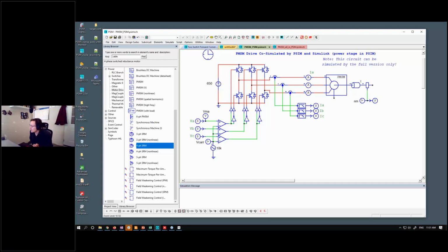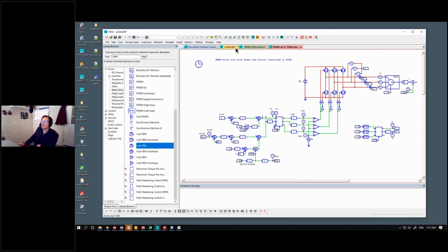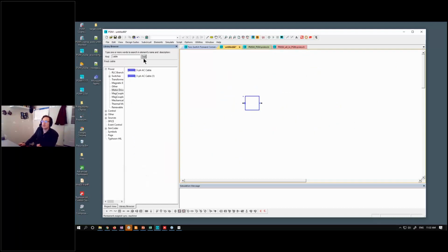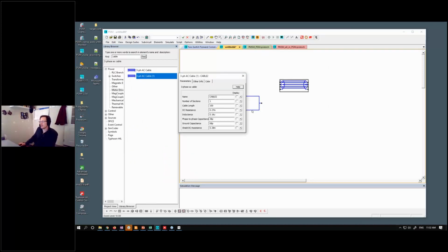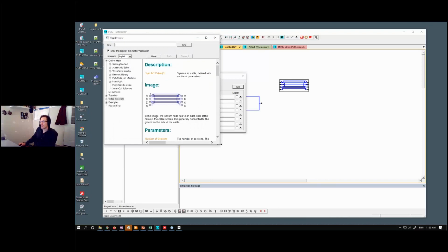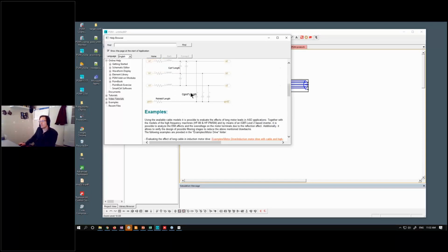So yes. Is there now an electromagnetic transmission line model in PSIM, i.e. a coax cable that takes RF effects into account? Looking back at this cable model we can put in, this is the equivalent circuit that we have, which is RLC with coupling capacitors to the phases and then one common shield.